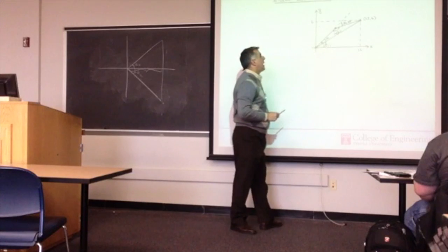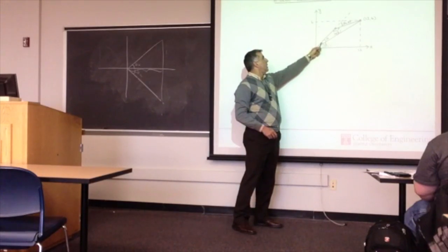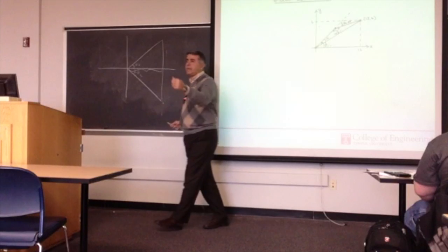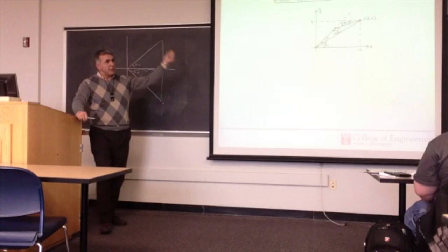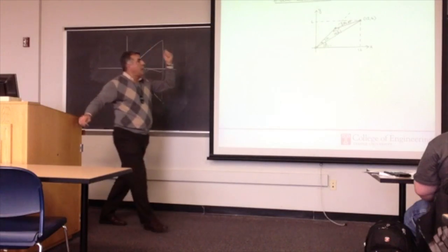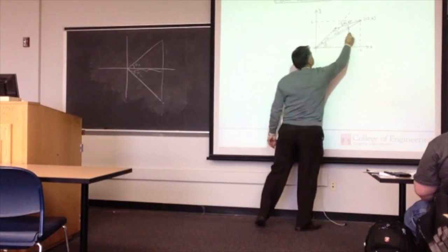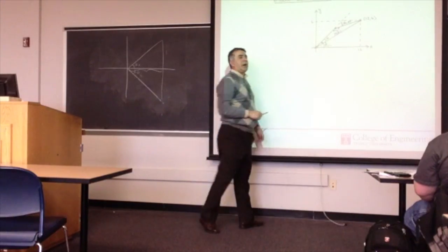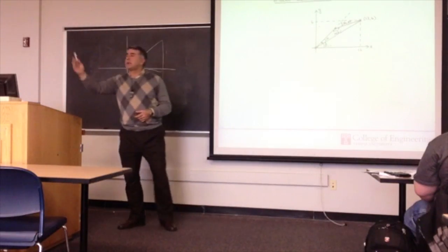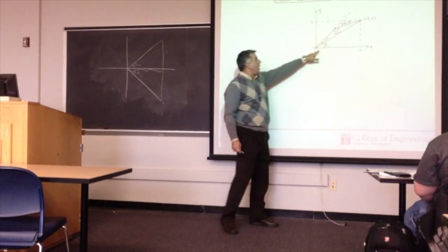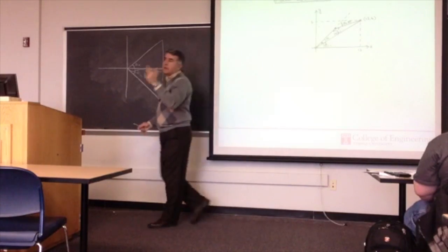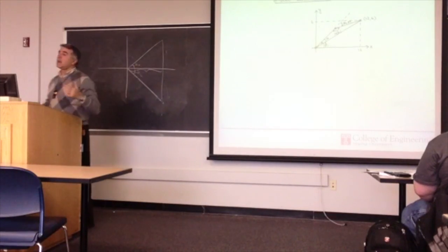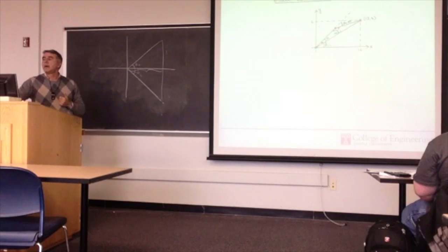Now you notice that in this case, theta 1 is the angle that the first arm makes with the x-axis, because that's where your motor is. And then theta 2 is the angle that it makes relative to the first arm. So that is why you have theta 1 minus alpha in order to get that angle, which is different than the other one, which was theta 1 plus alpha. Do you remember? Yeah?